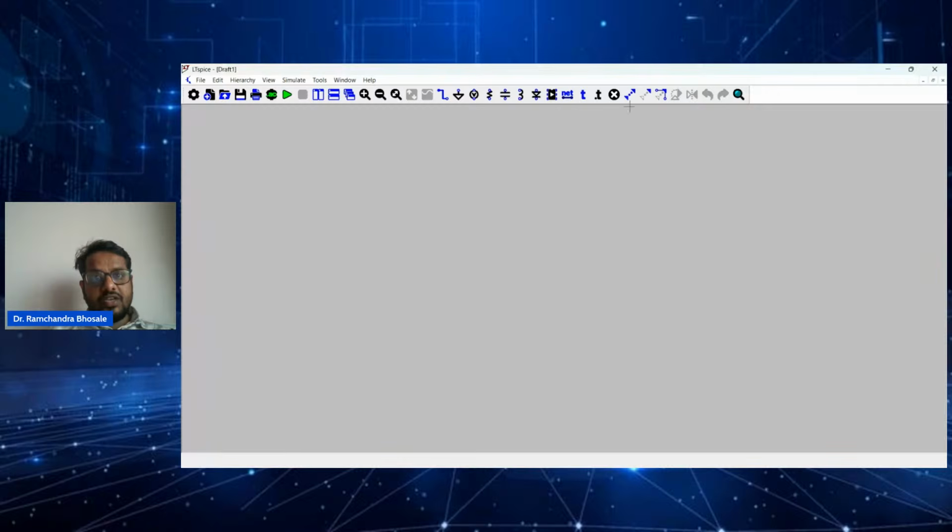Okay, so here you have different tools, and I will introduce them to you. This is resistor, capacitor, inductor, diode, and these are the IC section. And this is the ground section, where you can add the ground label. So I'll create one file. I'm going to File and New Schematic. Okay, we'll start with the buck converter preparation.